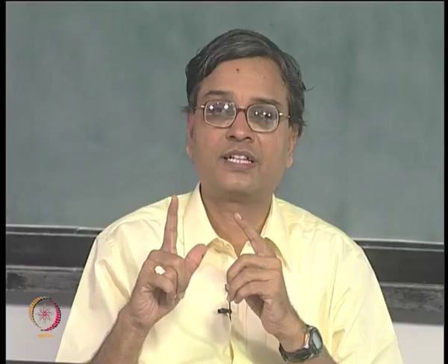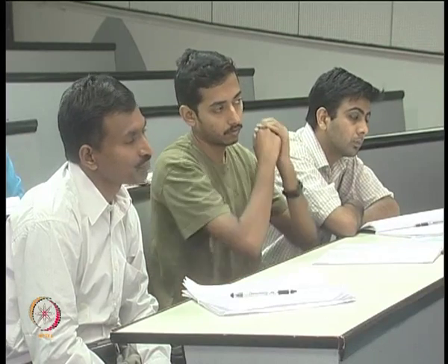If you want to look at that, Moire is the only technique which can reveal that. So, you have to select a technique for a given application. Now, you have digital image correlation, you have grid method, these are all for large deformation problems, but for small deformation you have to use, if you are able to use a strain gauge, well and good, I can go up to 1 micro strain, but I can't put a strain gauge on the electronic packaging, because that is comparable in size. So, you will not do that, and if I want still finer measurement, I can go to holography and find out very small displacement. For nano mechanics, people use holography very well.